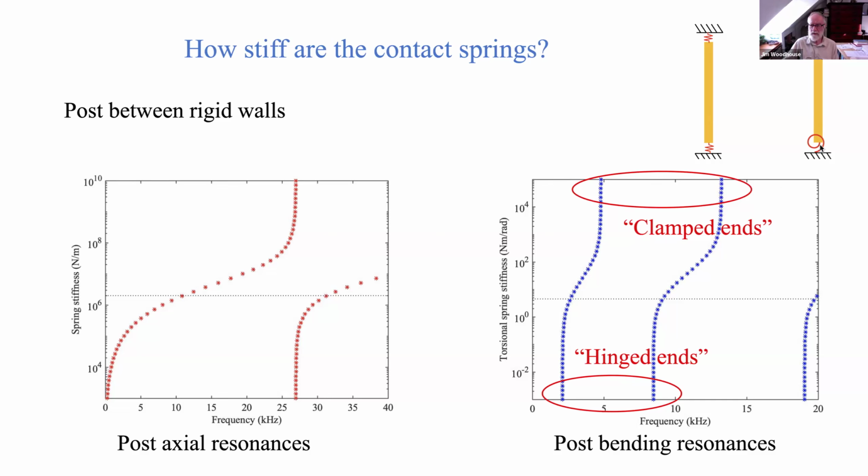With a super loose post sitting on one edge, it's still carrying the axial load, but the torsional stiffness has gone to zero. But the post, well, we're assuming the post doesn't fall down now, but it's as if there was a hinge at both ends. And so the post can still vibrate in bending ways, and it vibrates like a bar, a beam with hinged ends.